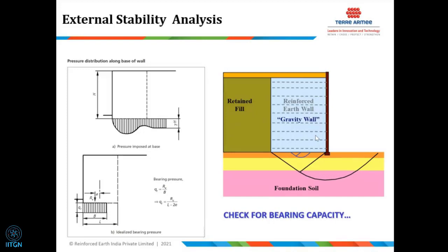The concept on the right hand side, sorry, we wanted to explain, because a lot of times we also face this difference of using plate load test for evaluating the foundation bearing capacity. I try to give you a scale of the structure of the Terzaghi's distribution. A plate load will never give you, even if you apply all the corrections, the correct way of checking the bearing capacity. It's better to just use the Terzaghi's equation and check the bearing capacity, and also not by local shear failure, but by general shear failure method.